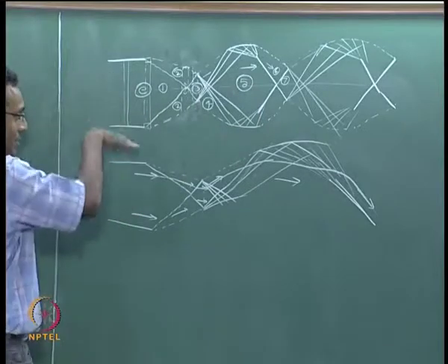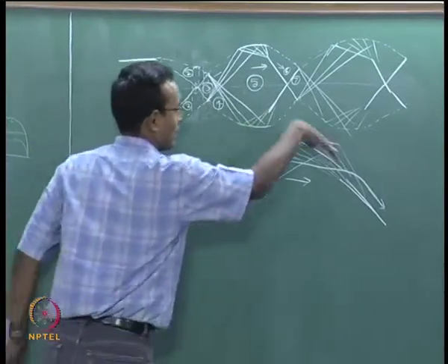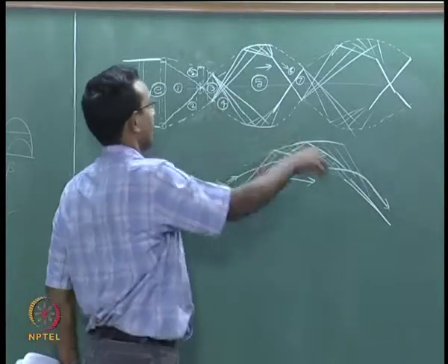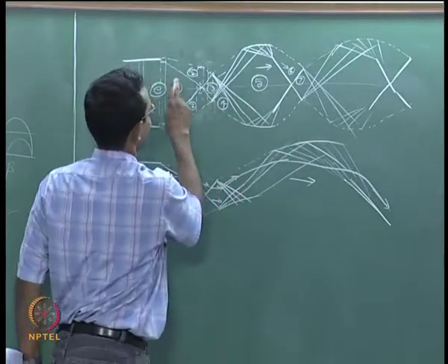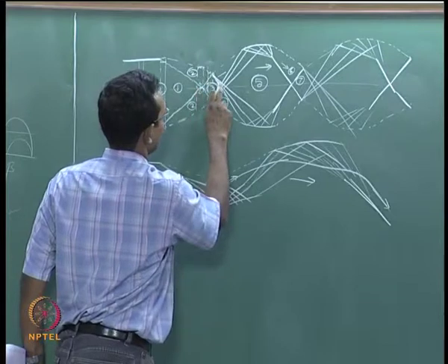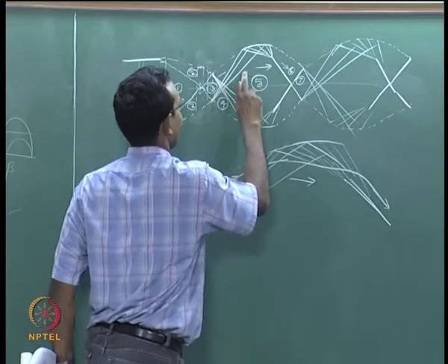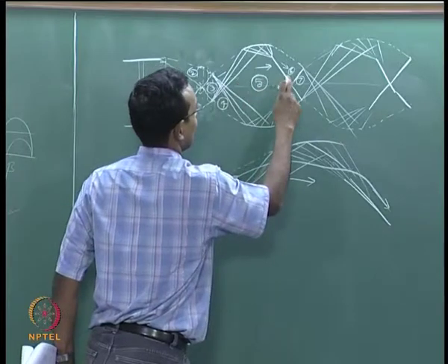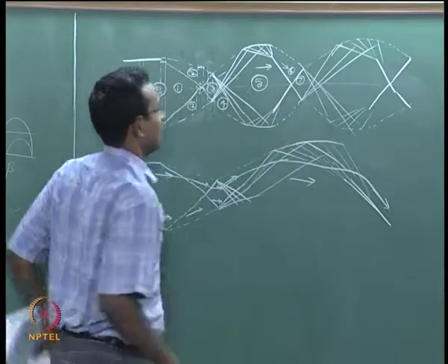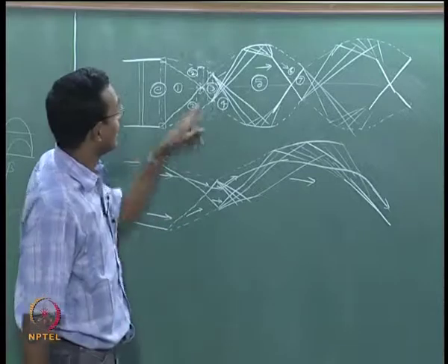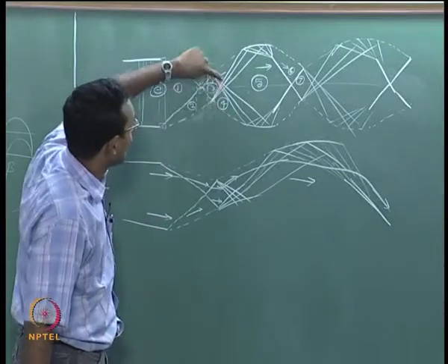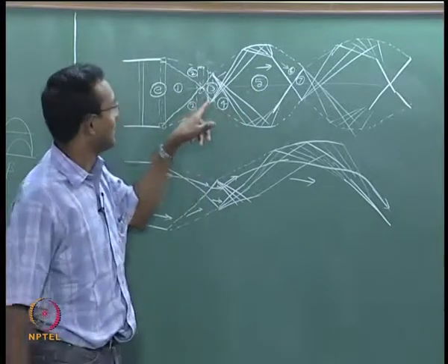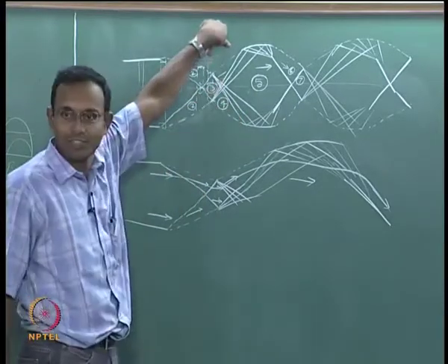It is going to be going down, coming back out, going in, coming back out, in a wavy fashion. If you look at it here, it is going to come straight, go in, go straight, go out, go parallel, go out, go parallel up to here, jump in, come back straight, and it just keeps doing this. In those points there will be a small region where the pressure is exactly correct. That is the pressure it had to achieve, the outside pressure.